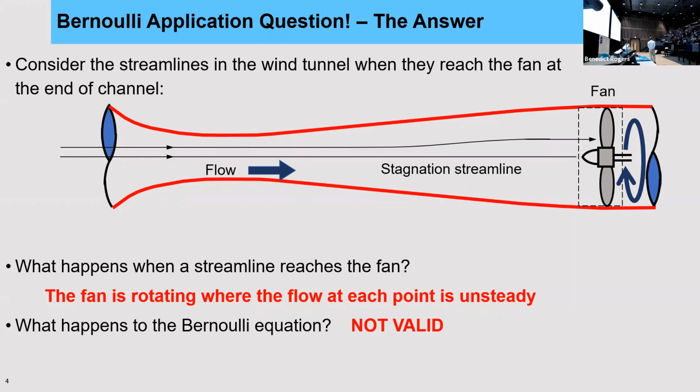The answer is really no, but it also depends upon the Mach number of the flow. In very low flows, where your Mach number is very low, yes, you might get some disturbance propagating upstream, but we have to be at a very low flow. Wind tunnels, by design, are looking at rather higher speed flows, and so when you start to get towards much higher Mach numbers, then the disturbance does not have the opportunity to propagate upstream. But I like your question because you're really thinking about the problem.